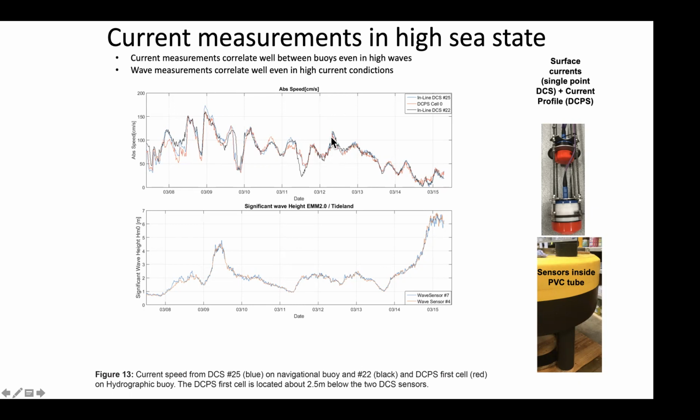But basically what this gives you, since you're using 2 sensors, one single point with a high frequency and one profiler with a lower frequency, 600 kilohertz, you get an independent quality control of your profiling sensor, at least for the first cells here. If they compare during most of the time in many situations, then it's a good indication that the quality of both these measurements are good.